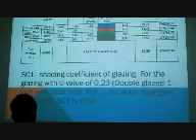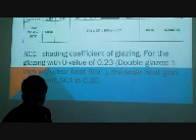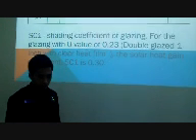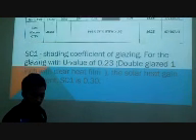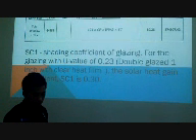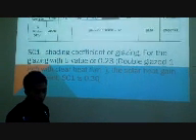And next we go to solar heat gain through walls. For this part, we have to find the shading coefficient SC, equal to shading coefficient 1 times shading coefficient 2, and SC1 is the shading coefficient of glazing. For the glazing with U value of 0.23, the solar heat gain coefficient is 0.30. So the next step is we have to find the SC2.